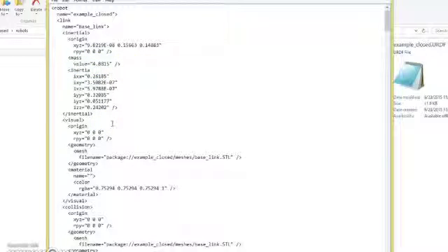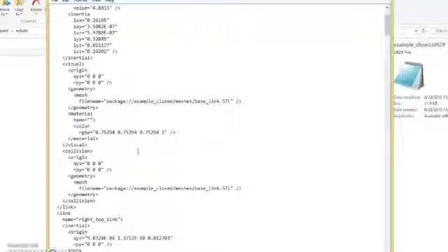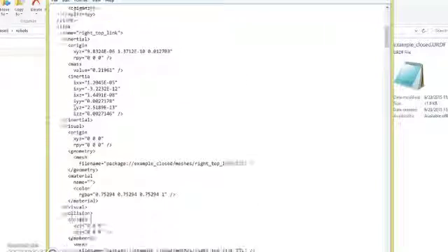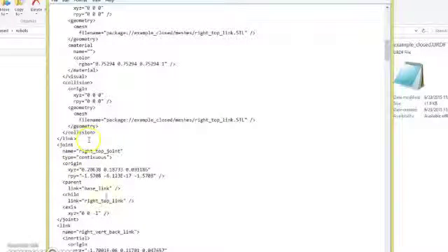The documentation on how to create an SDF or URDF is pretty strong, and the meshes that you'd use here you can include. So if you wanted to create a mesh using a different package and put your own link and joint descriptions, that is something that's possible, though it can become somewhat of a handful. So for instance, we see our visual mesh and our collision mesh, along with the moment of inertia of the link. And then we can see some joints later on.